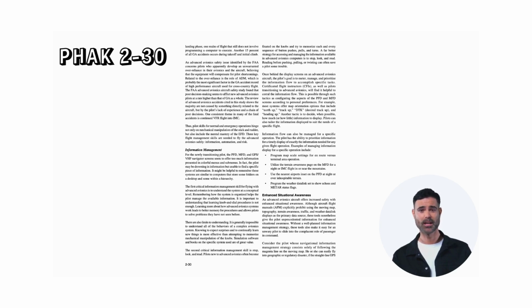Information management. For the newly transitioning pilot, the PFD, MFD, and GPS VHF navigator screens seem to offer too much information presented in colorful menus and submenus. In fact, the pilot may be drowning in information but unable to find a specific piece of information. It might be helpful to remember these systems are similar to computers that store some folders on a desktop and some within a hierarchy. The first critical information management skill for flying with advanced avionics is to understand the system at a conceptual level.